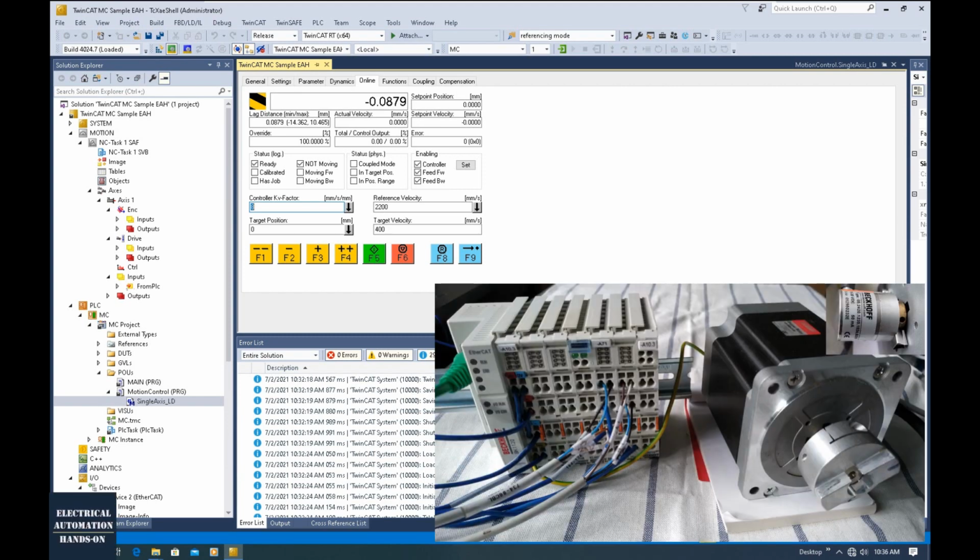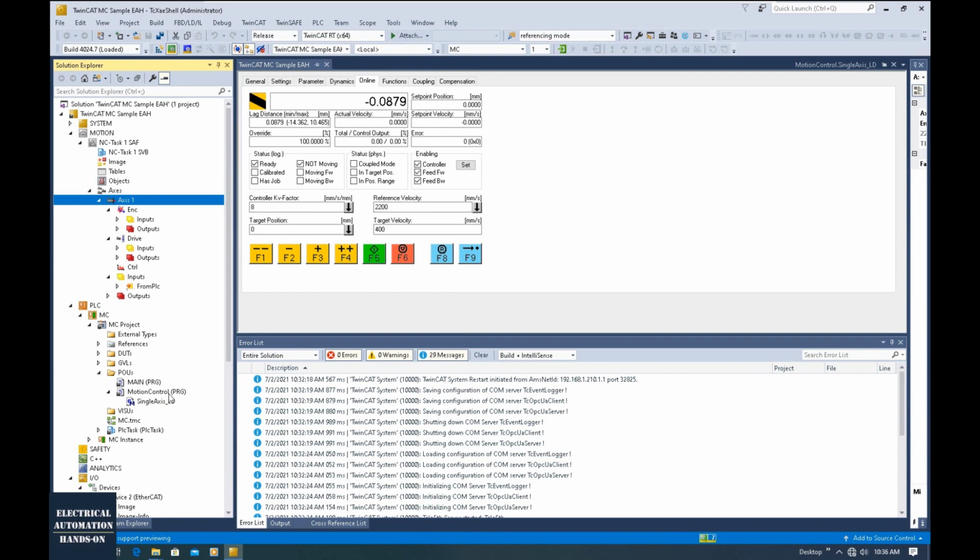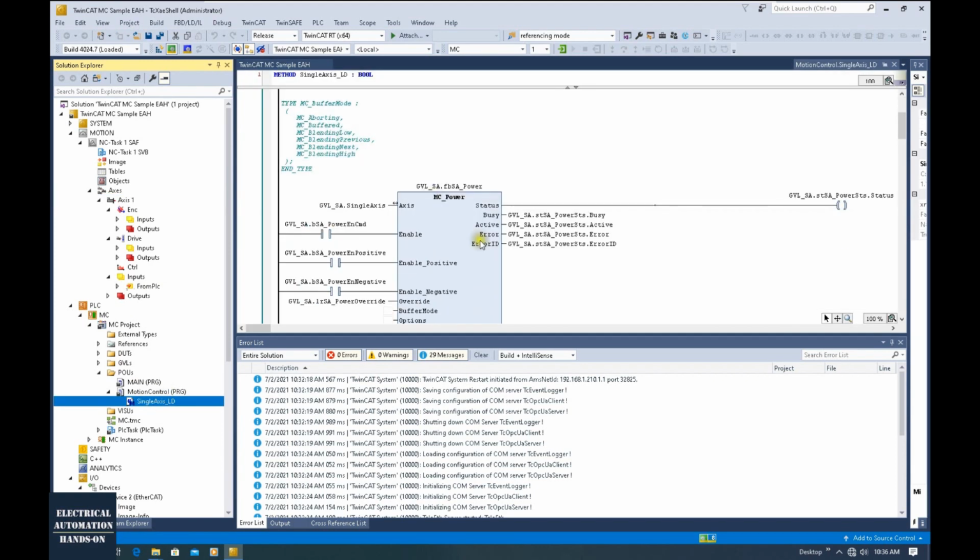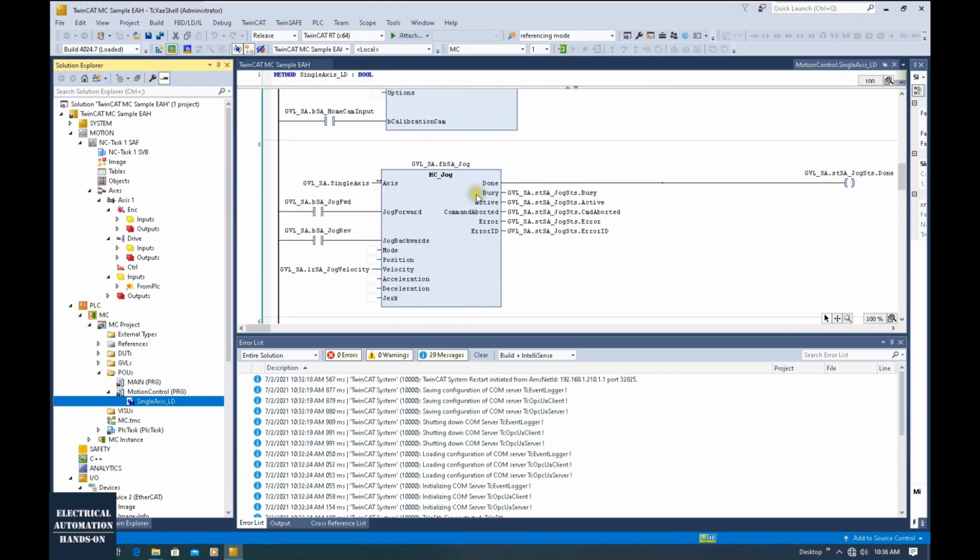In this video, I will show how we can connect our axis. This physical axis, connecting the step motor with the encoder for precision loop control, to our program. Basically, we will connect the physical axis to the program logic, for example reset, power on, home, and jog, allowing the program to control our physical axis.